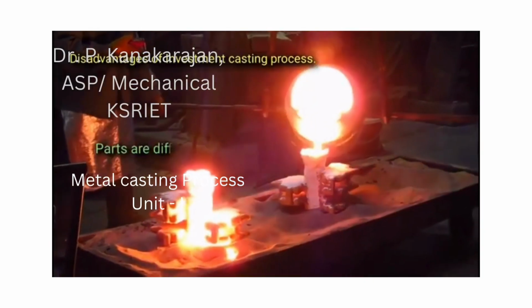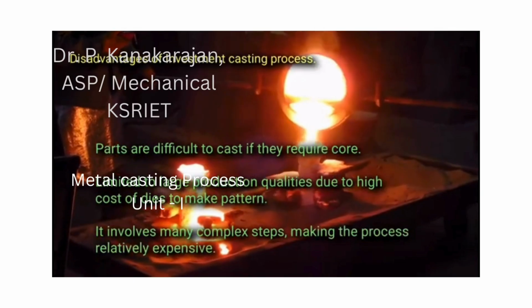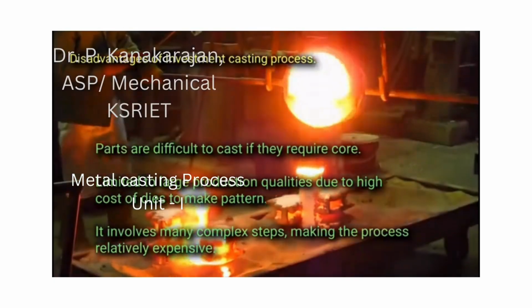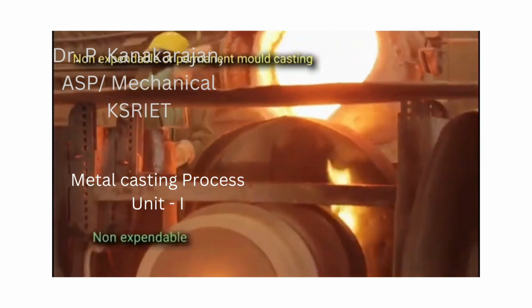Disadvantages of investment casting. Parts are difficult to cast if they require a core. It is limited to large production quantities due to the high cost of dies to make patterns. It involves many complex steps, making the process relatively expensive.